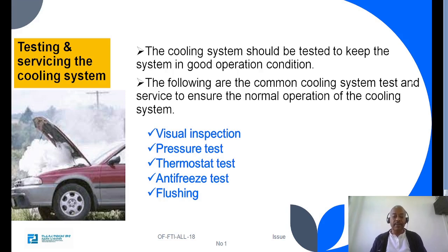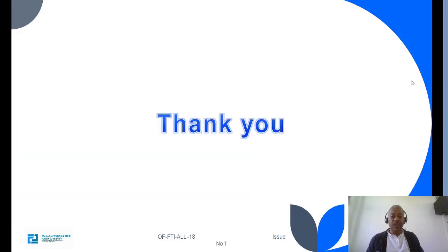The pressure test. The cooling system should be tested by the cooling system pressure tester. Thermostat test. The thermostat's operation should be tested to detect whether the thermostat is working properly or not. The antifreeze test and flushing. So all these different types of tests should be carried out in cooling system servicing.